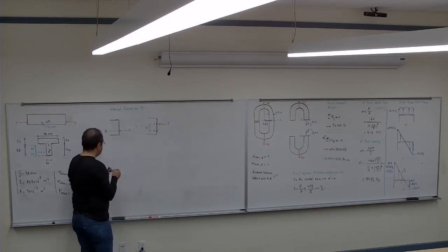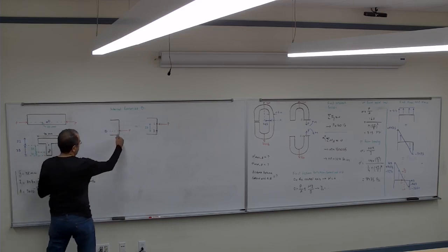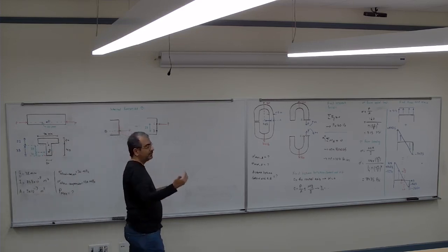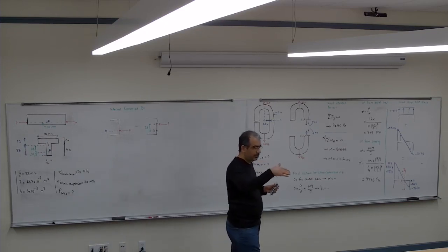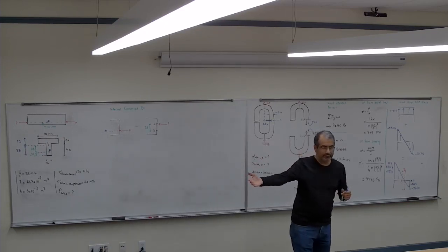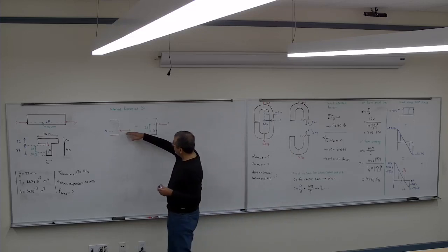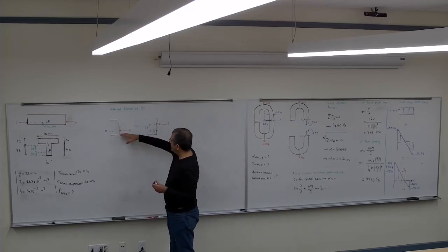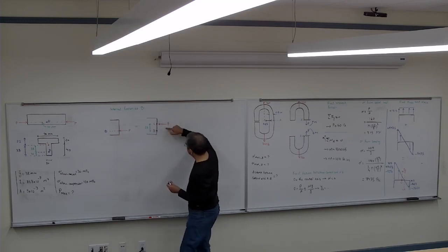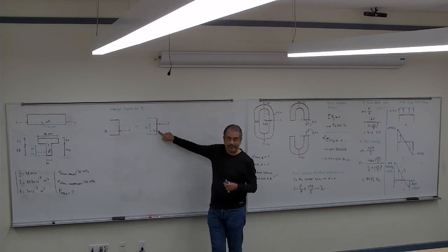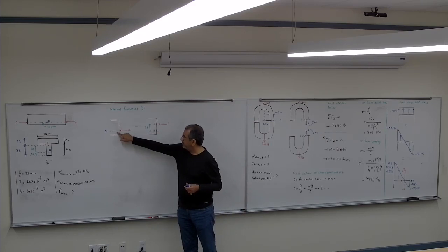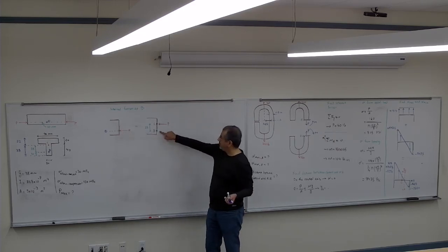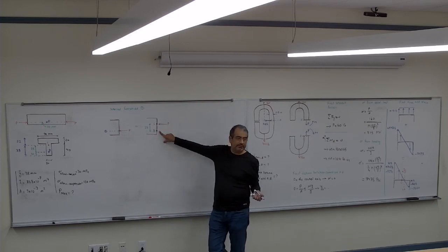Remember from statics, if I move the force from one point to another point, I have to add or subtract the moment that force causes by moving. So here, when I have it, there is no moment at that cross section. But if I move it, there's going to be more moment about D. So if I write a sigma M about D, the moment is 0. If I write a sigma M about D, the moment is not 0 anymore.